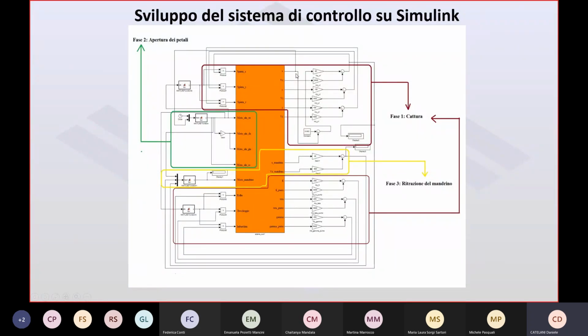In Adams, we evaluate position, orientation, velocity, forces, angles, etc. The logic manages this data, introduces some control, and then transfers back to Adams the movement for changing the roll, the pitch, the yaw, the longitudinal, lateral, to open the links, etc.